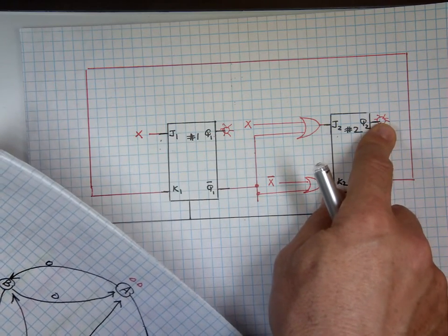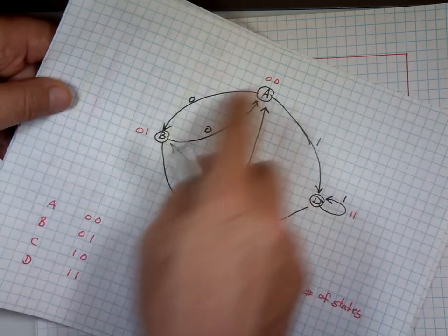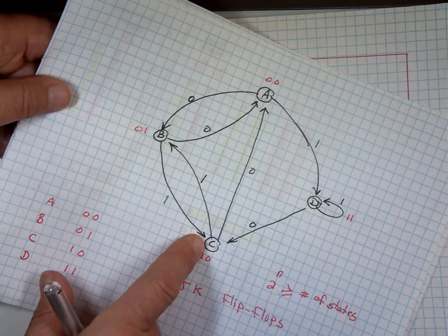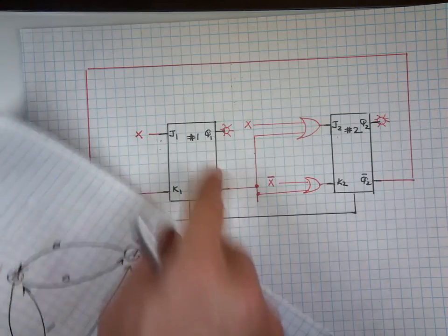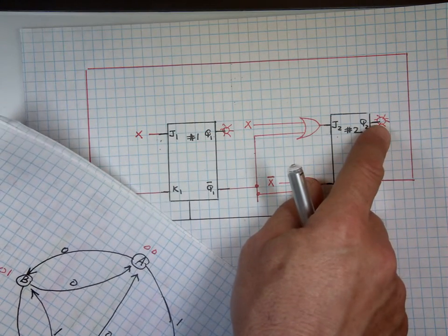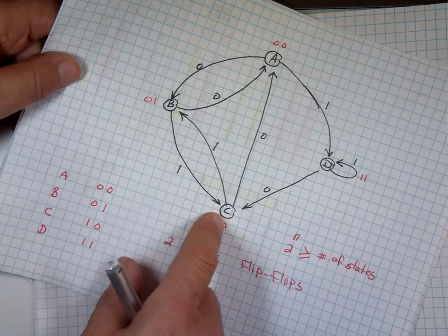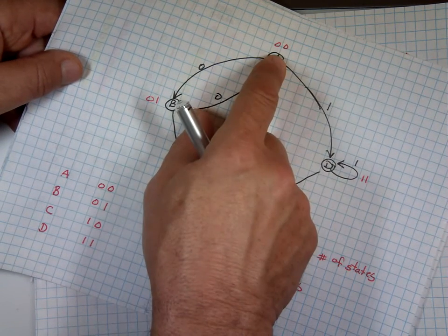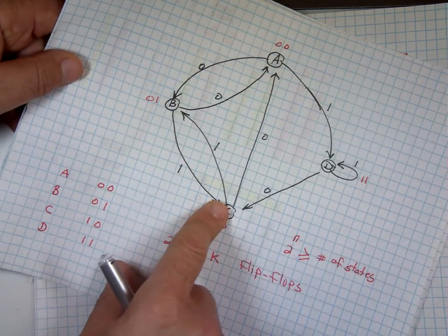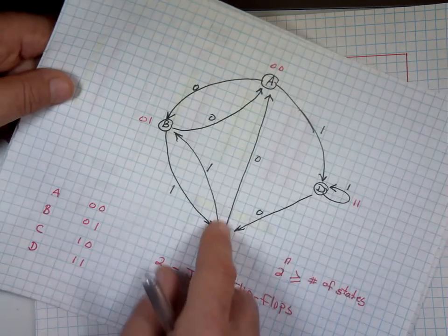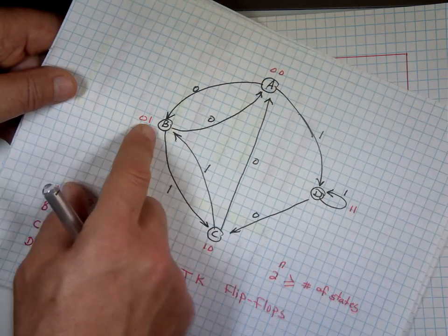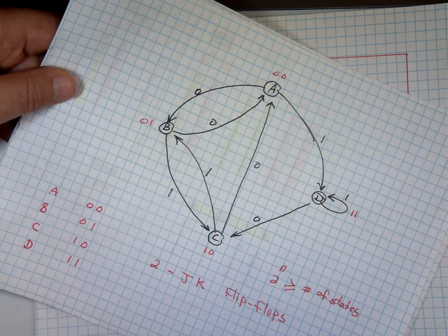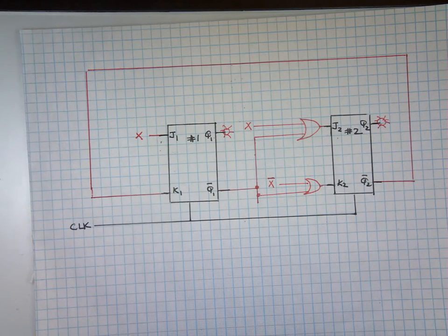Then you go, okay, let me move X back up to 1. If you move X back to 1, guess what happens? It goes to 1, 0. This light will be on, that will be off. I'm here now, and if I make X 0, it goes back right there. If I take X and move it to 0, both of these lights are off, but if I make X stay at 1, I'll go back to this one. There's only one actually input, outside input, and that's your X. And based on that, where you are and what X is, that will tell us the direction we're going to be traveling in, where we're going to be next.